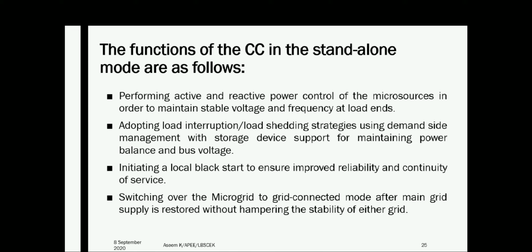The functions in standalone mode are as follows. It performs the active and reactive power control of micro sources in order to maintain stable voltage and frequency at the load ends. It also adopts load interruption or load shedding strategies using demand side management.